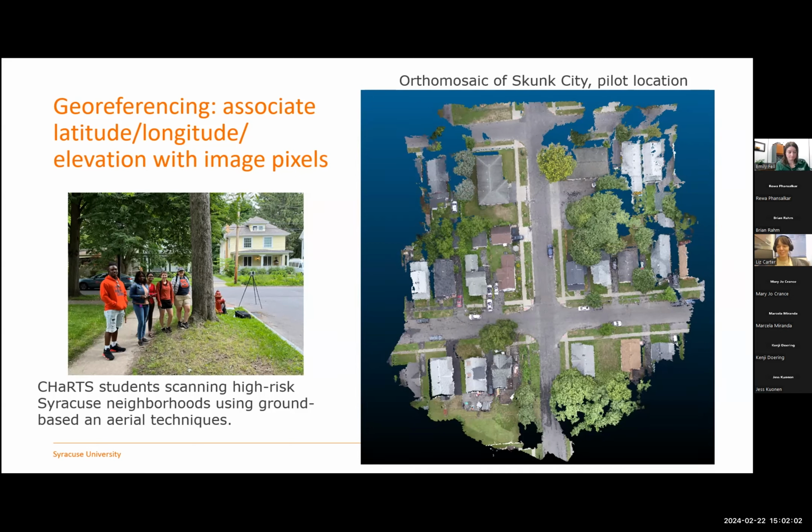We then use another type of artificial intelligence algorithm to find out where those images, many images taken of the same thing, overlap based on common features that are observed in the images, and we can reconstruct very detailed 3D representations of space in that way. If we have that 3D photogrammetric model of a neighborhood, and we install a stationary camera with a footprint overlapping with that 3D model, we can use the common features between what our camera sees and what exists in the 3D model to get the latitude, longitude, and elevation associated with each pixel in our camera's field of view.